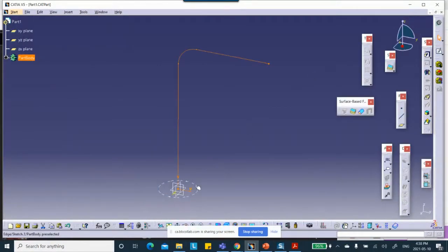Okay. And can anybody tell me what I have to do to make that part here? Can somebody tell me that? Don't be shy. I don't know who you are. Say that again. Sorry. Is it the sweep function? There is no sweep function in CATIA. Well, at least there is no sweep function here. Could you rib it? You have to rib it. Yeah, rib. R-I-B. Yes, yes.